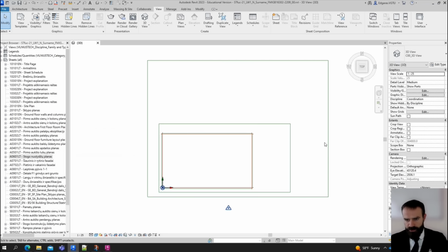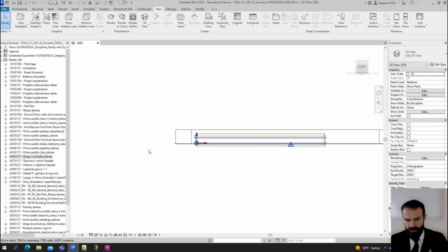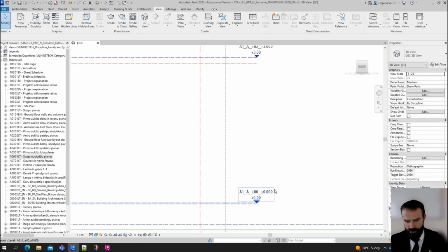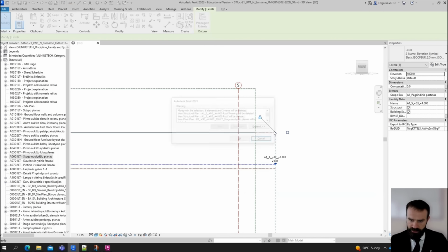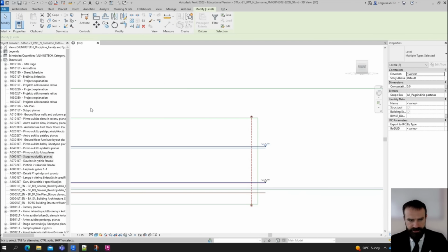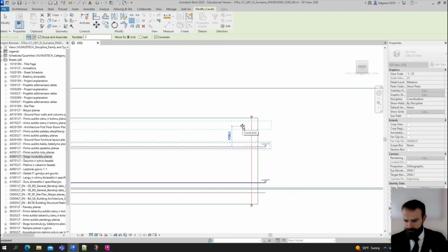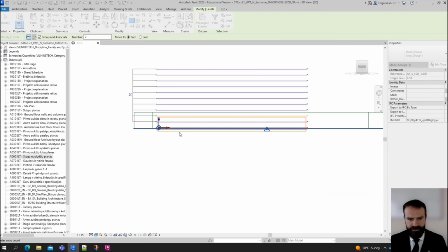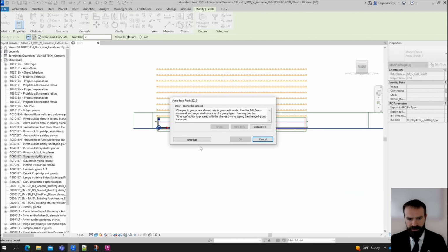So from the top view, I modify my scope boxes, and also I need to do the same from the front view. So if I have my elevation here, I can, let's say for now, delete this one, and I can copy paste elevations up. So I can use array tool and let's say my building floor here is 3 meters. And I can say I need, let's say 10 floors and I create 10.